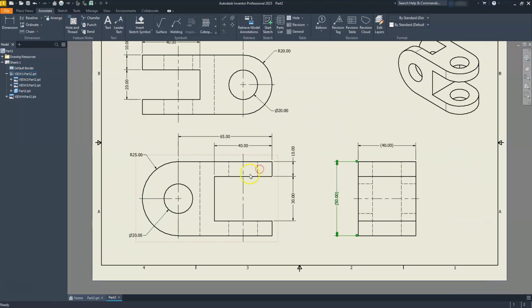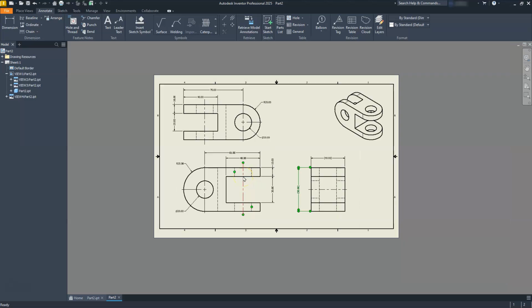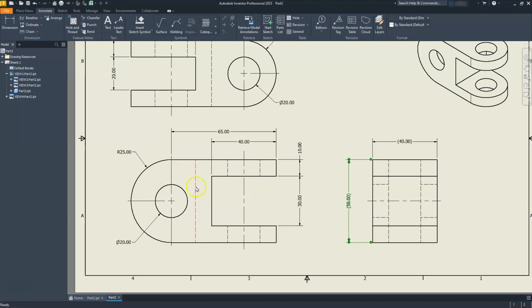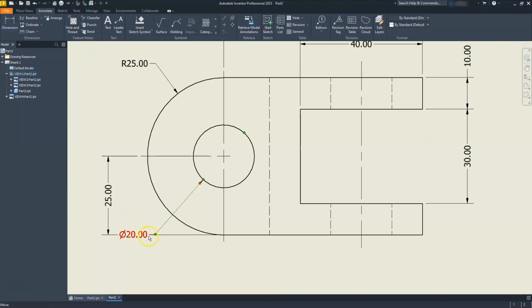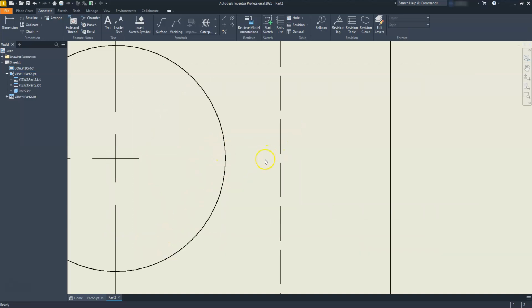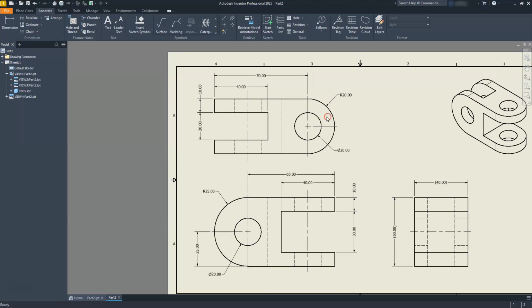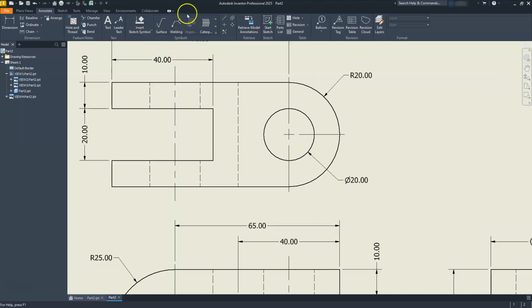Okay, just trying to look over my drawing to see if there's anything else I forgot. I can put the overall at 90, should be able to figure that out. And then there's a couple more dimensions that are optional. I can put a dimension from here to here just to specify where the center is. Really not relevant. We can assume that the center of these is located at the center of my part, but it's always good practice to go ahead and do that just in case. Let's put one more dimension on here.